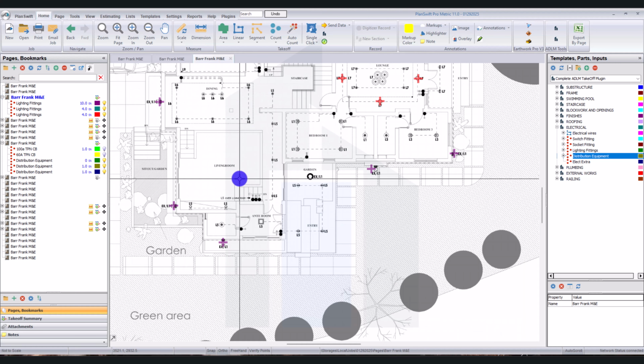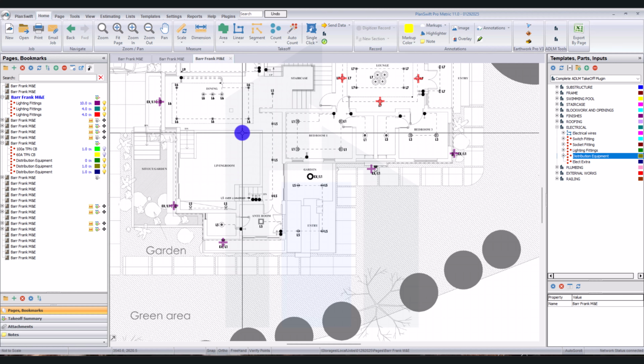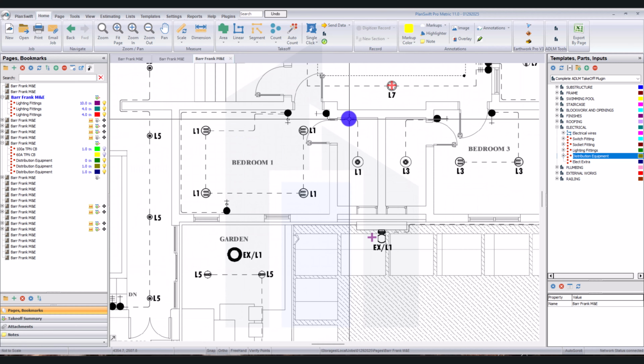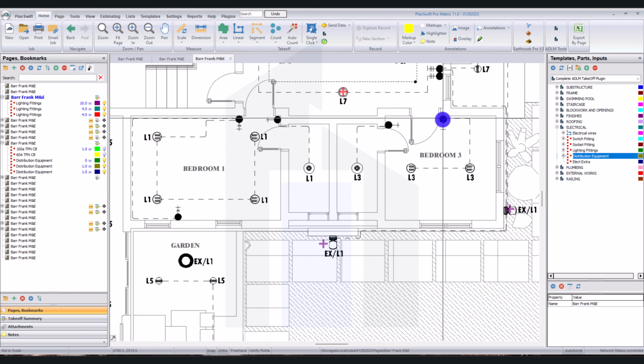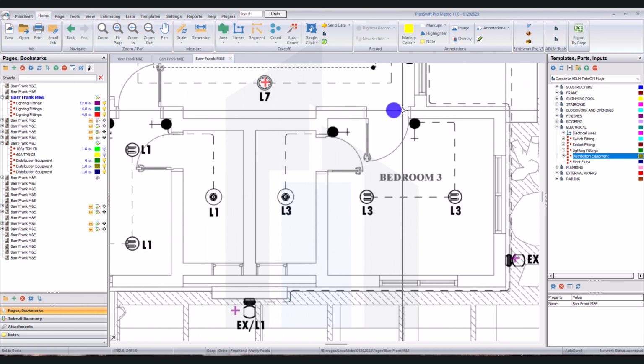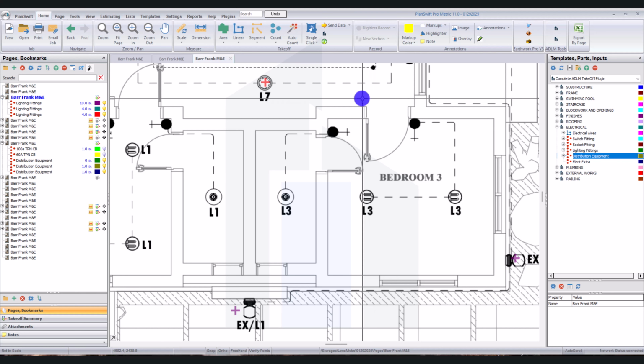So some people might just get electrical drawings and the drawing might not be scaled. What you can do is use the windows and doors to scale your drawing. I don't advise this regularly. So let's look for a bedroom door. By default in our area here in Nigeria, bedroom doors are mostly 900 millimeters. Okay, so I'll pick from the first point down to the next point. So I'll just click scale.